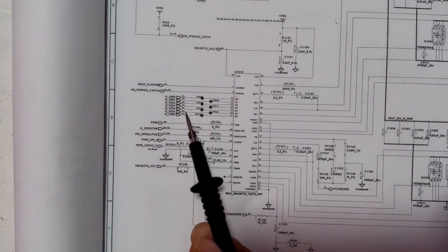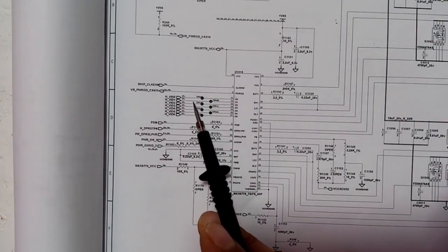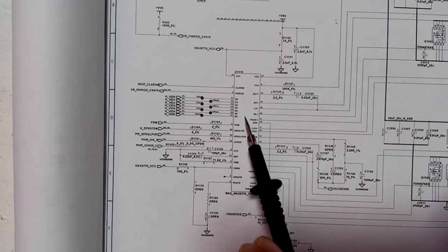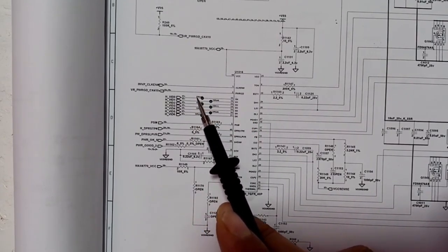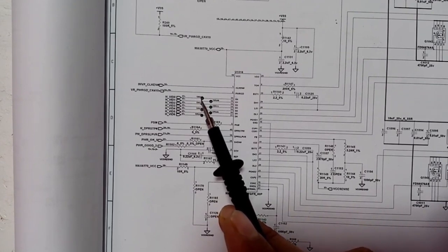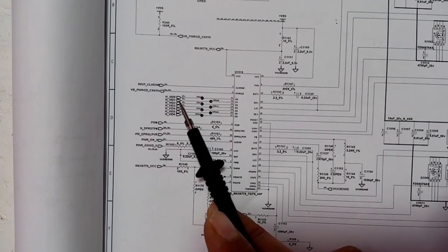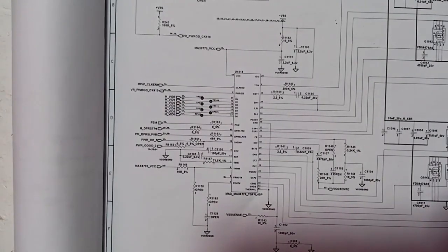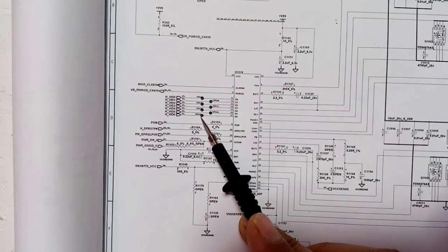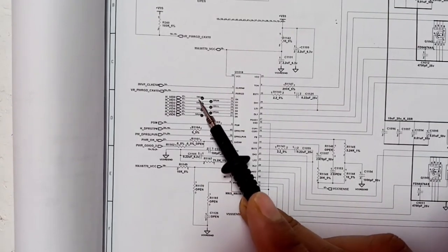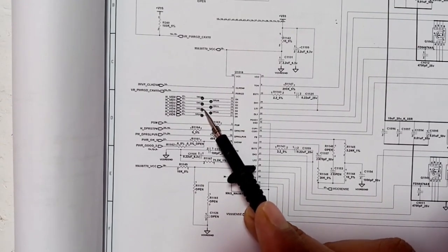And of course, in the motherboard, you can find near this IC a test point. As you can see, we have here TP, meaning test point, where you can check this ID. So let me show you this test point in the motherboard. Basically, we have the schematic and the real board, and we have 7 test points. So let's see in the motherboard.